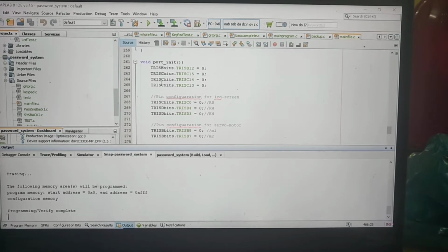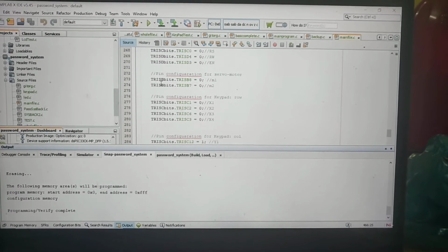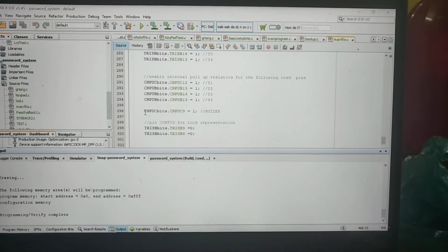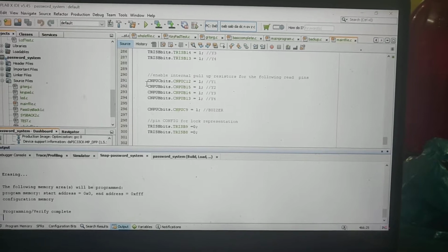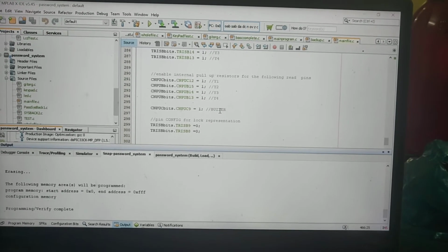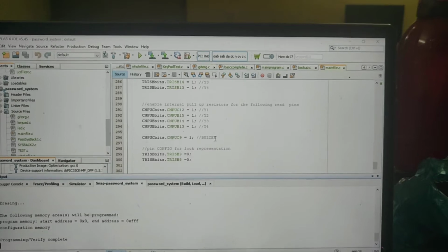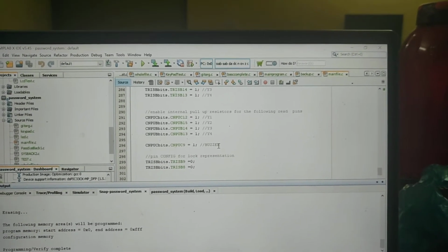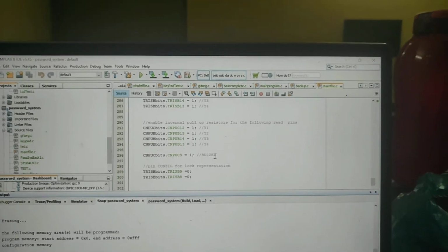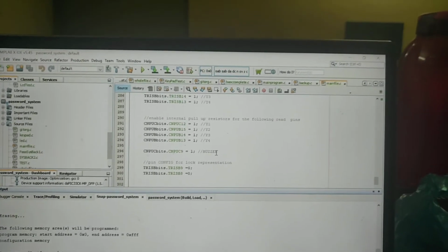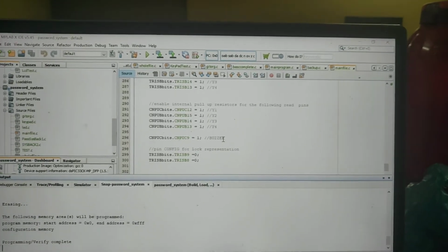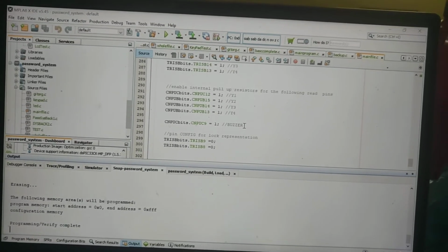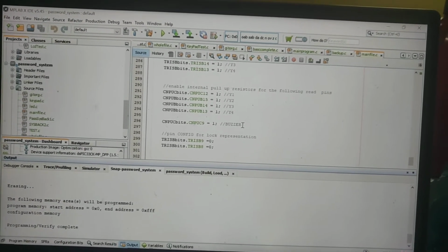This is to initialize the port, to let the compiler know which is the input port and which is the output port. I also need to enable an internal pull-up resistor for all the input ports, because without a pull-up resistor, the function might randomly choose between 1 or 0, and it is essential to maintain all the input ports for smooth operation, otherwise errors might occur while reading the ports.